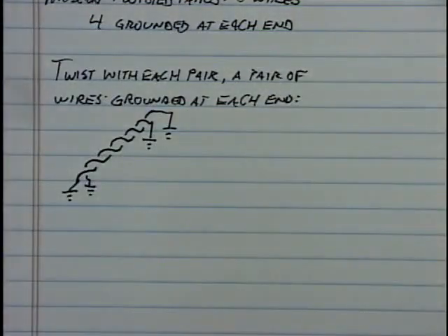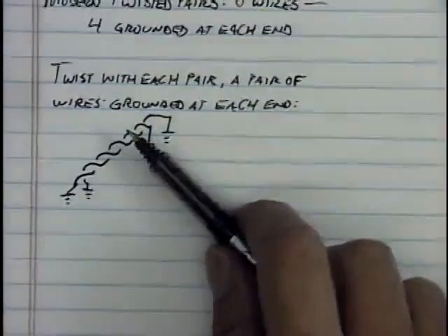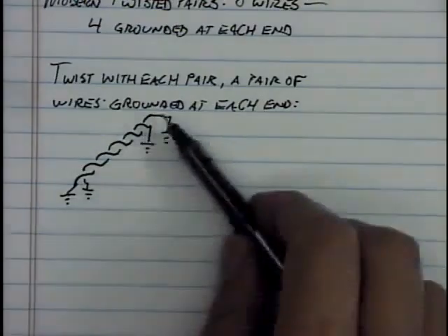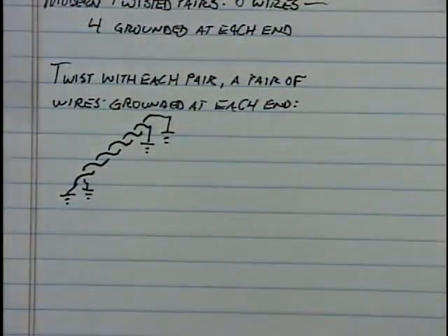Now, the idea here is that these dummy wires, these grounded wires, are really close to the transmit wires or the receive wires, which are the live wires. And any fields that aren't confined between the 2 live wires for transmit and receive, any fields that aren't confined right between those 2 wires will likely end up terminating on those ground wires rather than being radiated away from the 4-wire bunch.